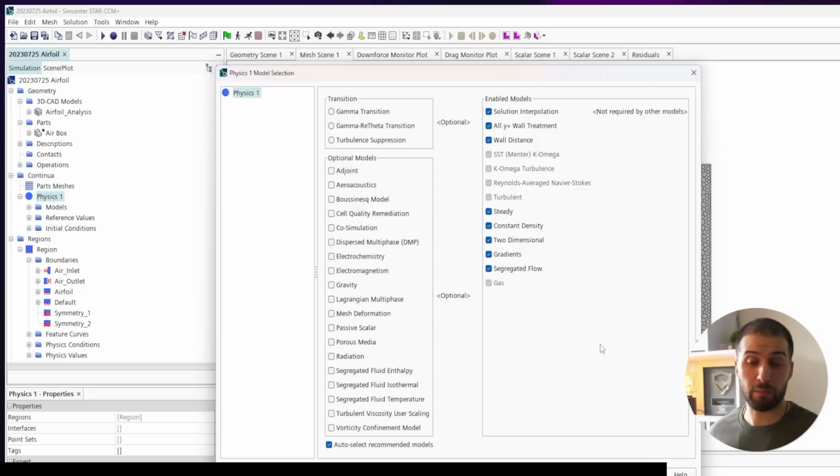Finally, the K omega model is typically more suitable for flows expected to transition from laminar to turbulent, as is usually the case for our airfoil. And some versions of the K omega model, like the SST model we're using, offer robust handling of transitional flows, which isn't really possible with the K epsilon model.